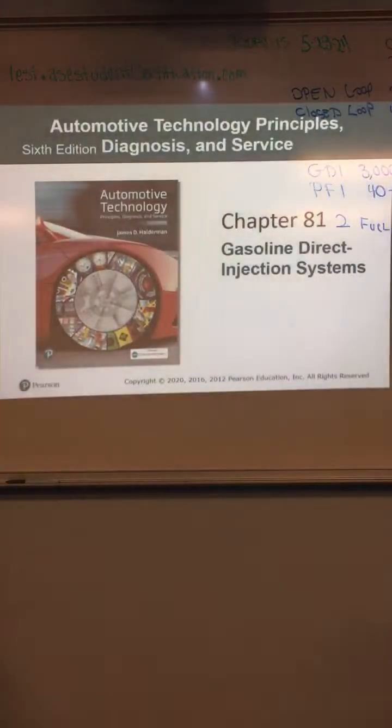What's the cam that makes the car sound choppy? On V8s, well, that is a cam profile that has a little bit different low lift and duration than the original. Normally, factory ones, they try to make them as smooth as possible so you get power out of them as well. But when you change to an aftermarket cam that has more lift and duration, you get that choppy idle.